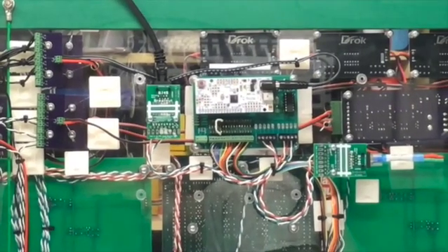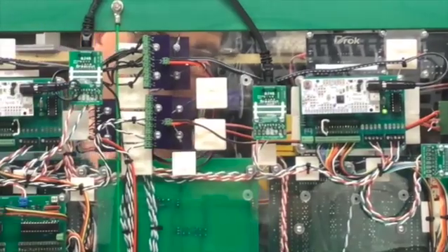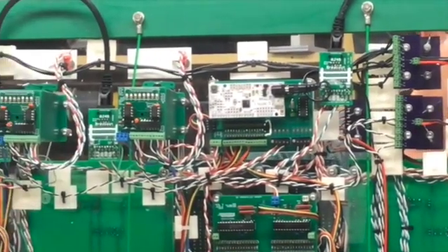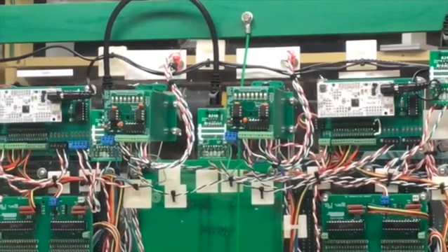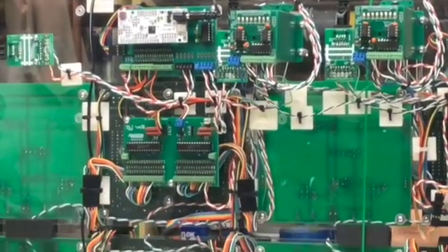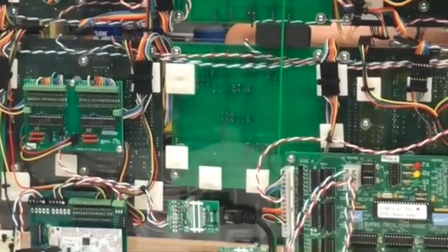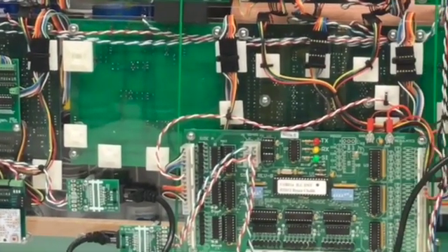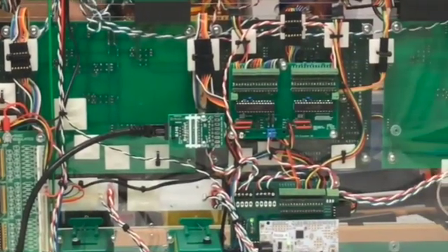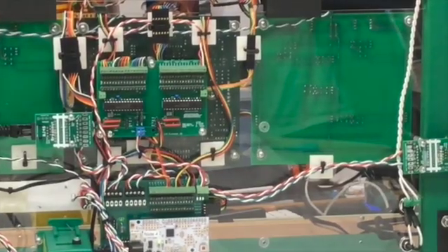When it comes time to convert the testbed to LCC, all we have to do is disconnect the I/O lines, remove the CMRI nodes, and cable in the LCC nodes. The actual conversion is a bit more complicated than that, but that's a topic for another day. One major difference between modular signaling with CMRI and LCC is that with the RR circuit signal LCC nodes, ABS can be configured to run without any host computer attached. Whereas with CMRI, a host computer is required to be up and running during the show. Both systems use JMRI and CATS, however, configuring CATS to work with LCC is still a work in progress.